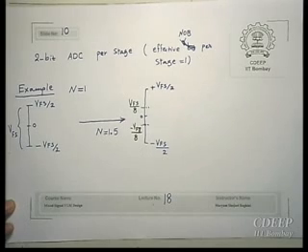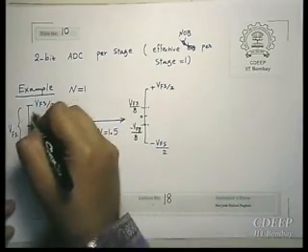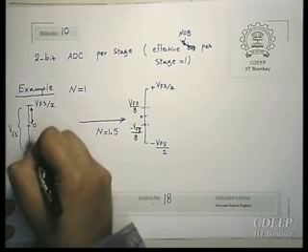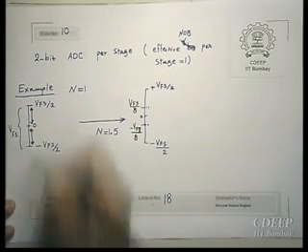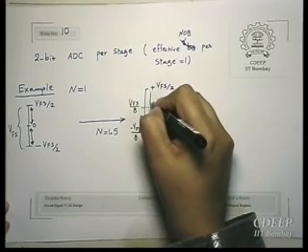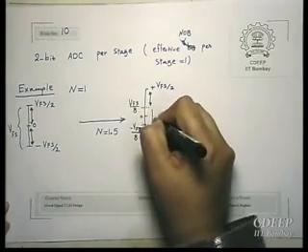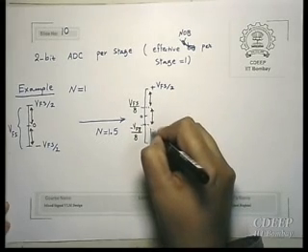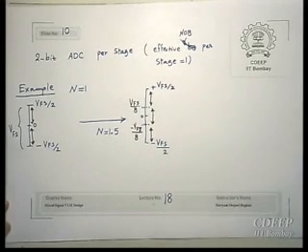Now, what we do is that here, how many intervals do you have? 2, right? And you check whether your input signal is in upper half or lower half. Here we divide it into 3, and these 3 are not of the same magnitude. So see, number of levels are not 4, they are 3, and you have 2 bits eventually. That's why it is called 1.5 bits.